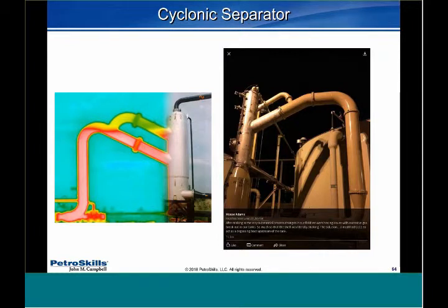This is something I pulled off of LinkedIn. There's a facilities engineer named Moose Adams, and he indicates that after making some very substantial process changes in our field, we were having issues with excessive gas breakout in our tanks, so much so that the shell was literally shaking. The solution was a modified gas-liquid Cyclonic Separator to act as a degassing boot upstream of the tank. And that's a really good idea. All you need is some type of device on the piping to disengage some gas and insulate it. It doesn't have to be this elaborate. And an improvement they could make for the wintertime is to heat and insulate that to get that last flash.